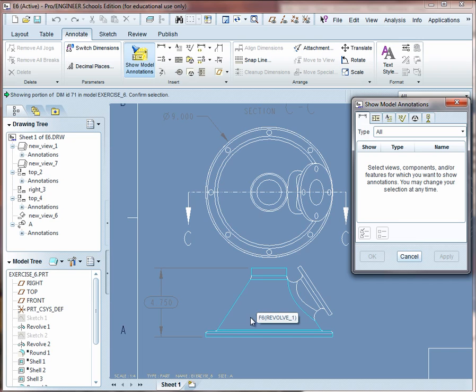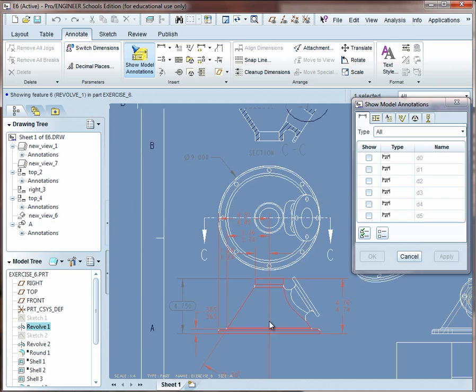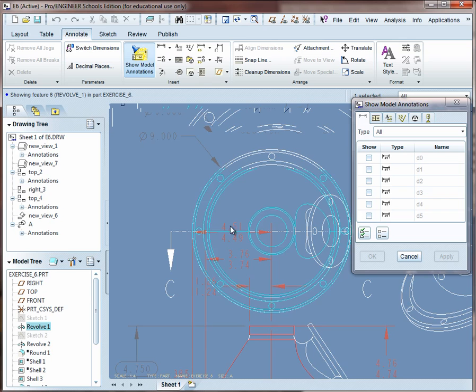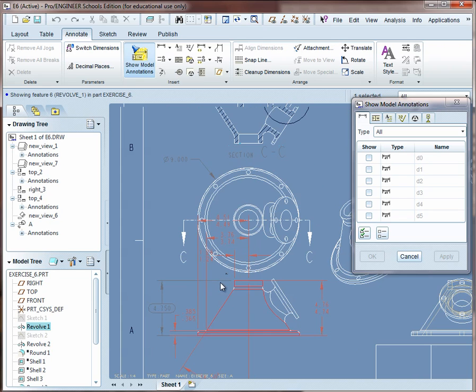In other words, whenever this was modeled, however it was modeled, using a profile obviously, it will bring up whatever dimensions it could find. So if I select it, you can see it brings up quite a few dimensions there. Now these are coming up with a dual display actually of a tolerance. We might want to adjust that. That's found in that File Options, and we could adjust that in just a little bit. But for right now, let's go ahead and put some of these in.